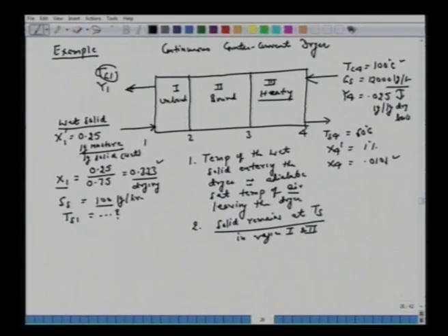All right. So before anything else, let's discuss what it does mean. If you recall in our previous discussion, we say that when we have a solid brought in contact with some hot air which has temperature Tz and humidity Y, the film on this, so if the solid is moist covered with some thin film, we are talking of this unbound region, the moisture will evaporate, water will evaporate, and the solid temperature will decrease till it reaches an equilibrium with Ts.